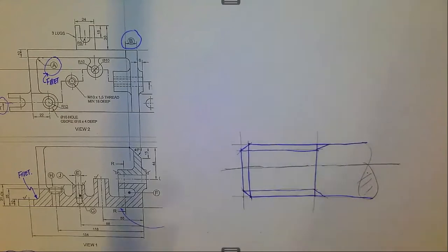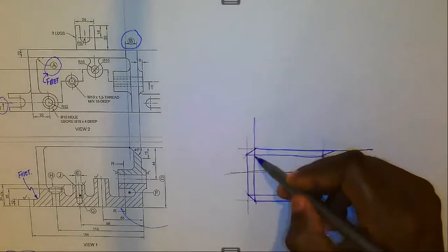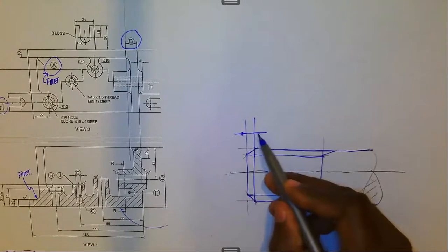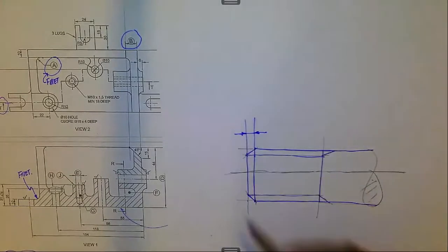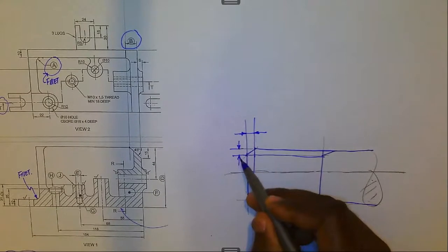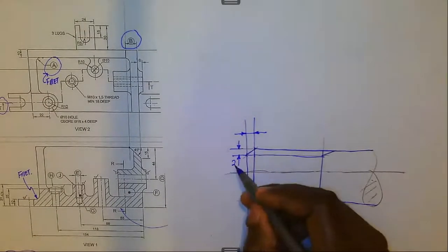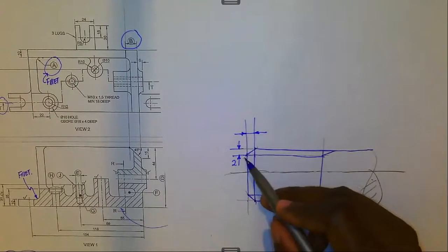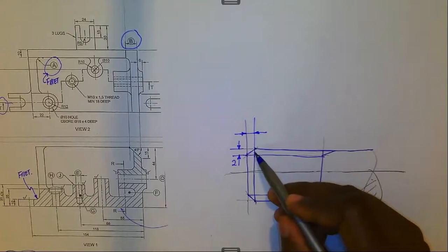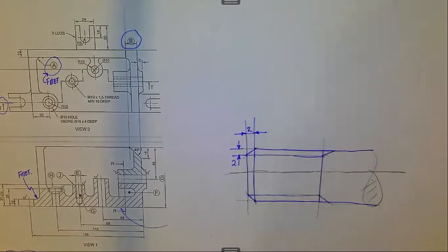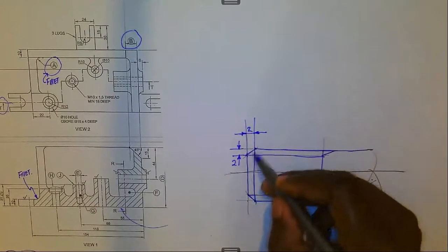The significance of what we are talking about is, if we are given the distance from here to there is not specified, but the distance from here to there is specified as, say, 2 millimeters like that. So what it means, if we make use of a 45-degree set square, this distance also is equal to 2 millimeters, simply because we have mitered that.